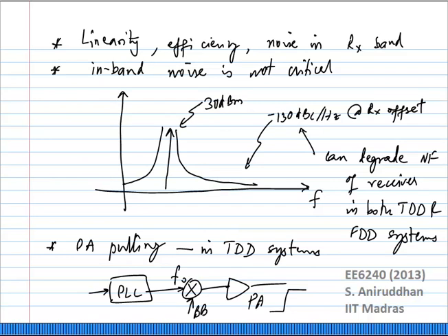However, in-band noise is not critical. Here you are not worried about things like the noise figure of the mixer, of the upconverter, right? Noise figure of filters and so on. You are more worried about distortion.